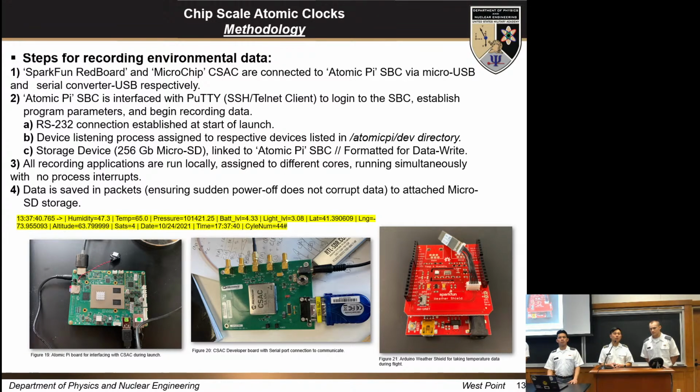That just depends on how good our oscilloscope or frequency counter is. The oscilloscope, I believe, is 2 nanoseconds at the shortest, and the time difference counter is in the nanosecond to picosecond range.